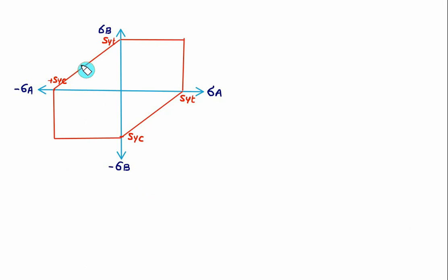So this envelope form here is valid for maximum shear stress theory. This one is for maximum shear stress theory, MSST. And for brittle material, we are using maximum principal stress theory. In that case, we have assumed the value of SUC greater than the value of SUT.